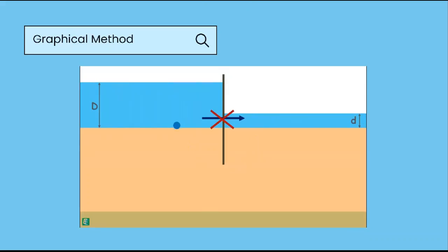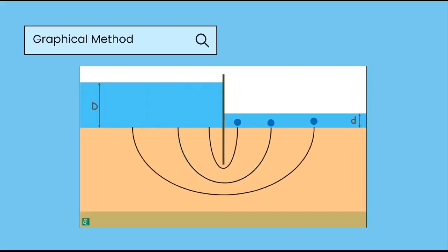So let us consider a water molecule enters the soil at some point on the upstream surface, goes below the tip of the driven sheet, and ends up at some point on the downstream surface. The flow path assumed by a water molecule is the flow line. Similarly, many particles will leave the upstream and reach the downstream, following different flow lines.